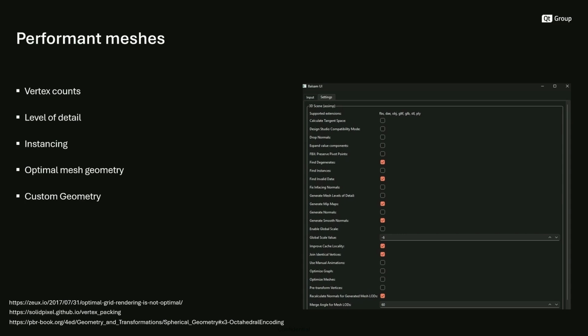One tip I can give is that if you have a detailed mesh that needs to be simplified, but you would still like to keep that detail in the scene, I would consider baking that detailed data into maps. So for example, a normal map to still keep that detailed lighting, or height maps for use in parallax shading.